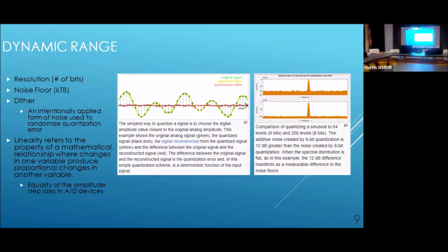It's coming. Here we go. Okay, so what's our dynamic range in the A to D? I'll tell you, it's a lot more with a decent A to D than any analog radio that I know of. But the funny thing is, the input stage of the A to D converter is still analog. So that single analog stage is the point at which the performance of the device is really going to be determined.